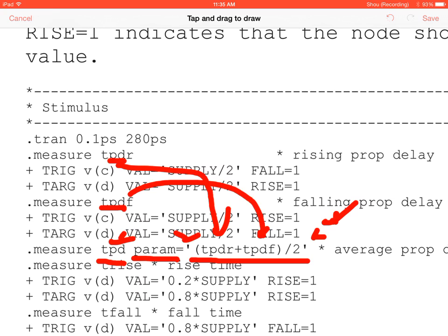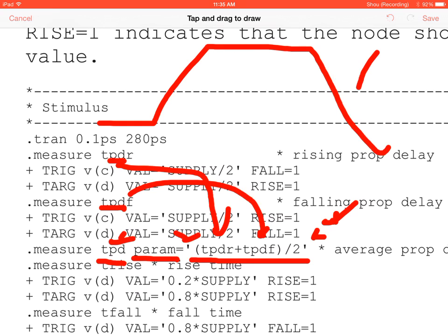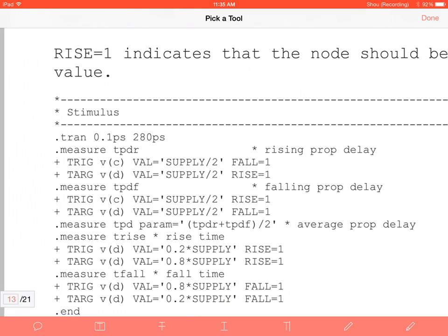So we did all those calculations back in section 2 to try to make the rise time and the fall time the same, right? So if you've properly designed your inverter, you should be able to measure rise time, propagation fall time, and total propagation, and these three values should be very, very similar. When you get to 10 or 11 decimal places, which you can regulate in your simulation, you're going to get very small differences just because of holes and electrons. But generally, they're going to be very similar.